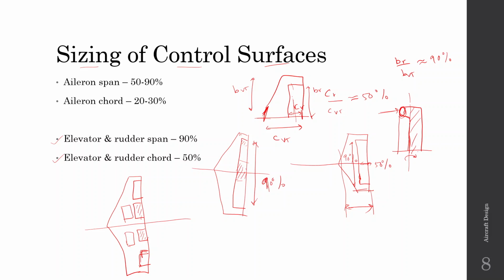This causes the aircraft to fall and decelerate, and it may be used to rapidly bring down the aircraft. Let us say you're flying at a high altitude and you have to rapidly come down, you can deploy the spoilers. Similarly, when you're coming in for the landing, after the aircraft touches the runway, the spoilers may be deployed so that the aircraft doesn't bounce back up. So there is no bouncing phenomenon.